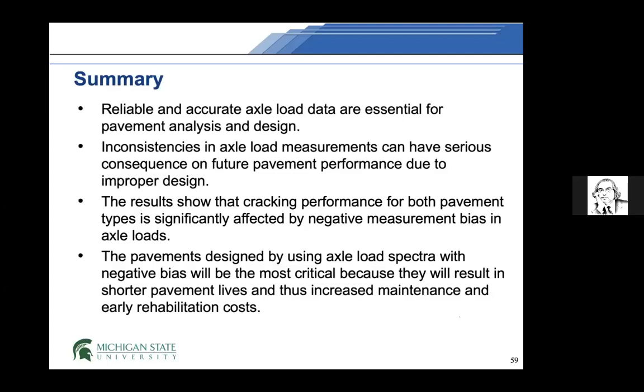By the way, we can calculate ESALs or truck factors from the axle load spectra. That's how they are collecting. And I'm not sure in Pakistan we have enough reasonable data to come up with our own loadings. I have seen people are using the fourth power law to get the load equivalencies. And I have seen ESAL values of 100 million, 150 million.